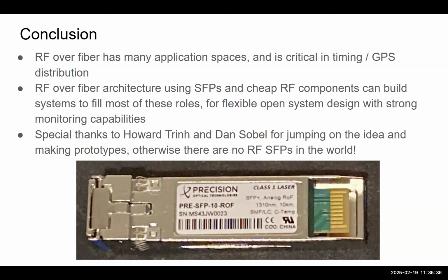And because it is a standard, we would easily be able to offer this in any variant that would be required, meaning a wavelength. If WDM were to be used, where you had to put, say, 40 different wavelengths on a single fiber, you could have 40 analog signals going across a data center or a building on one fiber. That'd potentially be an advantage, where the wavelength would be selectable by the end user or the customer.